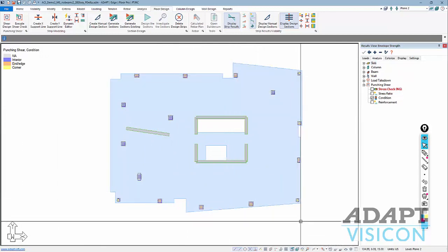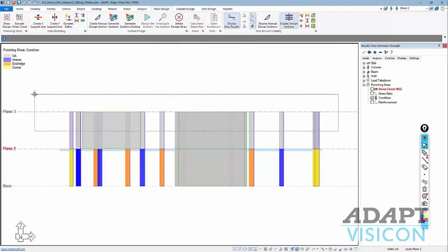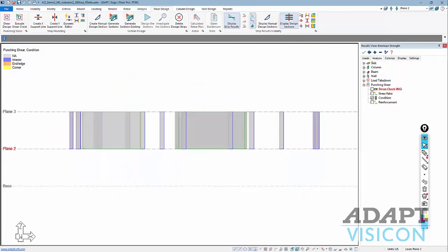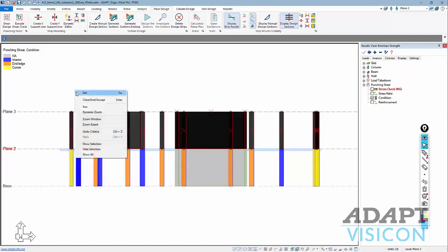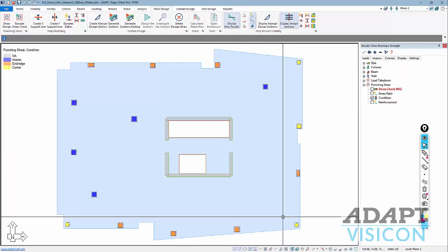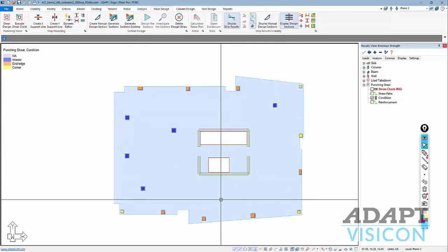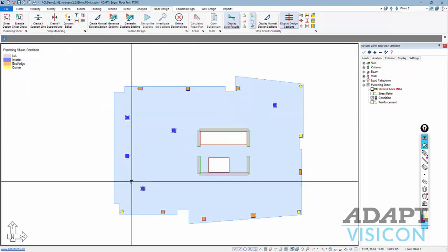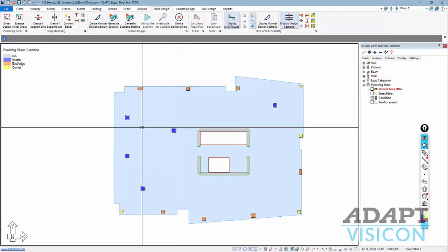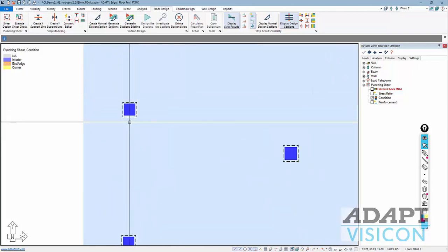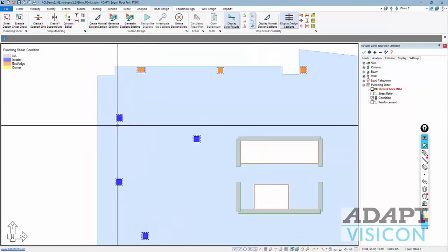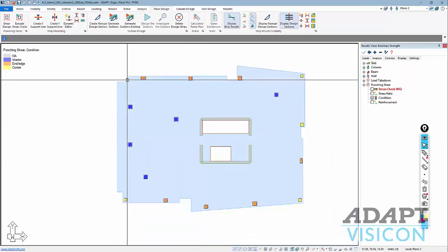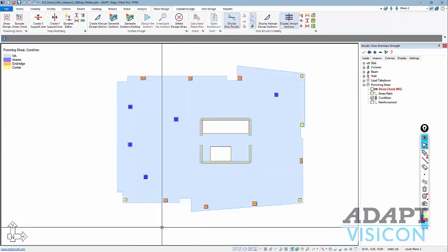You can see these colors are somewhat muted because we have this gray on top of it. So I'm going to select that and just say hide that selection. Let me try that one more time. Okay, and if I come back to this, the colors brighten up a bit, and it's easier to correlate here with this legend. So most of these, the interior columns are obviously four-sided, they're interior. This just gives an indication of the critical section shape that we're using at d/2 from face of column. This does not necessarily indicate every critical section shape, especially when we have the check made for the octagonal shape.